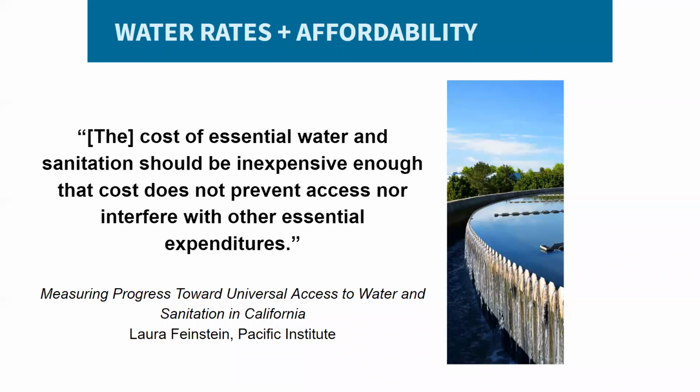Just as there is no single definition of water affordability, there is also no singular approach to measuring it. Many utilize the median household income of a census tract or a community and use the threshold of 2.5%, meaning if your water bill is above 2.5% of the median household income for your community, your water may be deemed unaffordable. This, however, is a general metric that may not accurately capture the impacts of a bill on any given household. And the approach was originally developed to measure the financial capability of an entire community to pay for infrastructure investments, rather than the individual or neighborhood level.